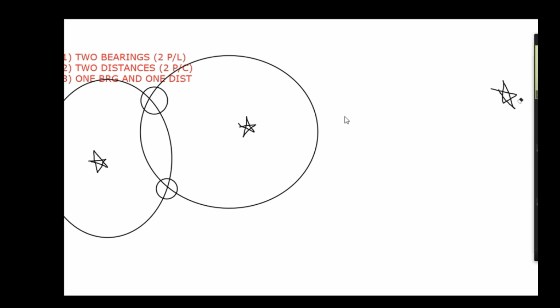We have done all intercept, etc. By doing the intercept or long by chron, what do you get? Long by chron you get an observed long, but the observed long is of very little use. The main important thing is your position line, because the vessel is on the position line; the vessel is never on the observed long. Observed long is not a correct long.